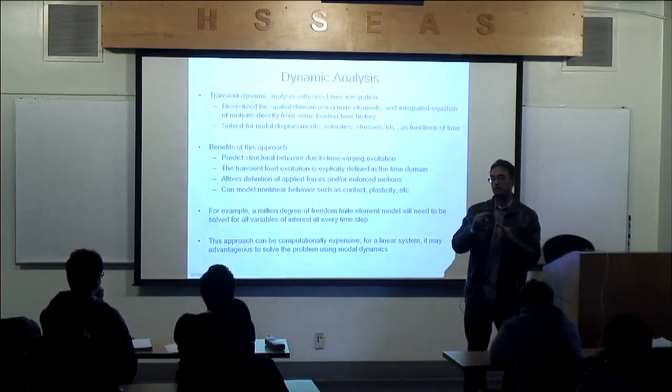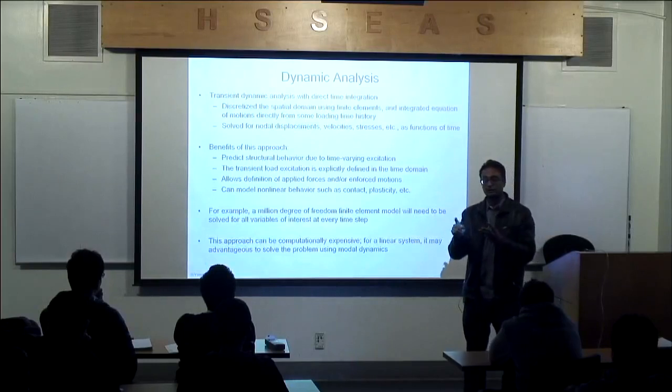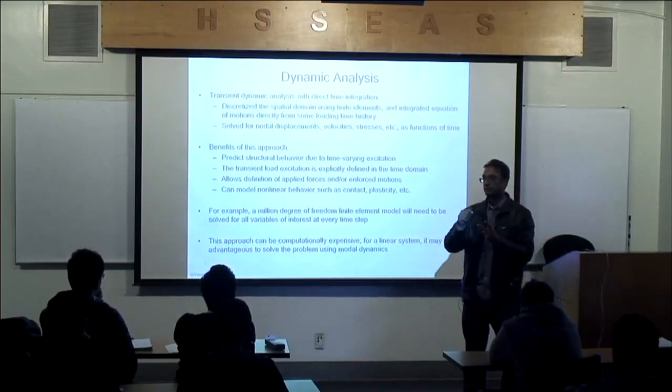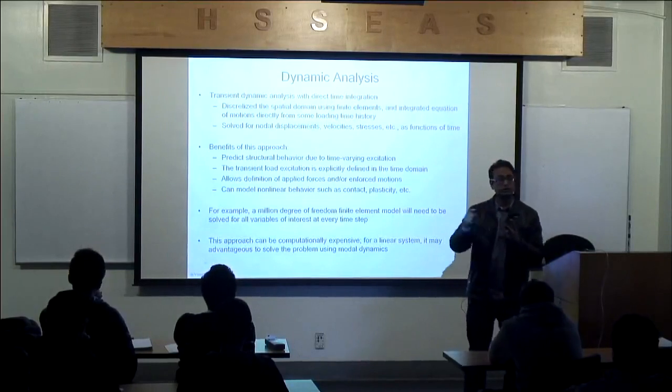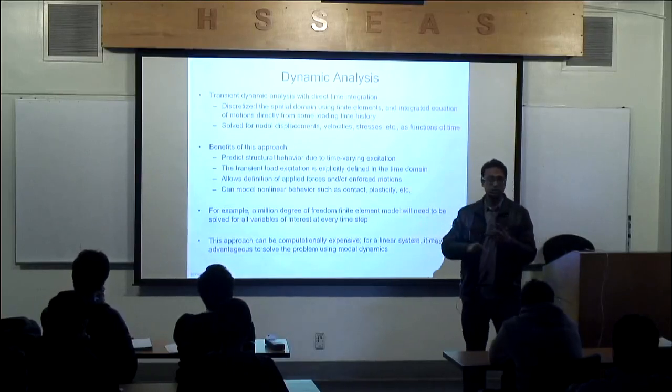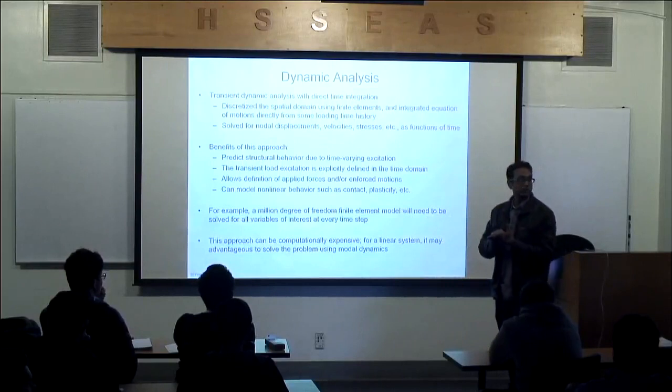Right, because I know how displacement changes over time, so then I know how velocities change over time, and I know accelerations, how they change over time. Not only that, if I know the displacements, do I know the strains? If I know the strains, I know how the strains vary over time. And if I know how the strains vary over time, do I know how the stresses vary over time? And I do know that through Hooke's law, and we've learned that. Okay.